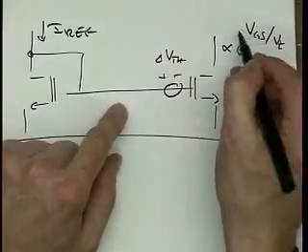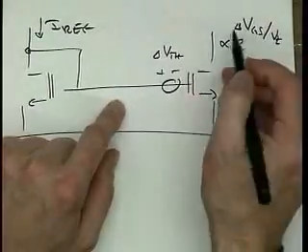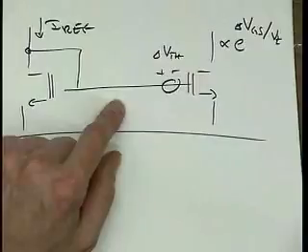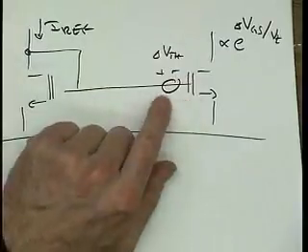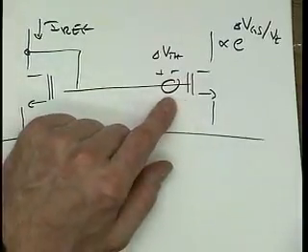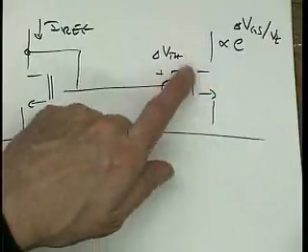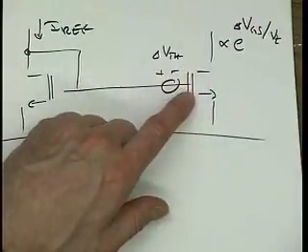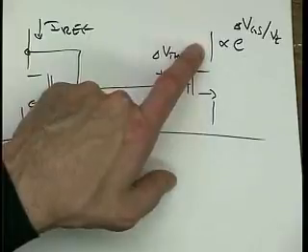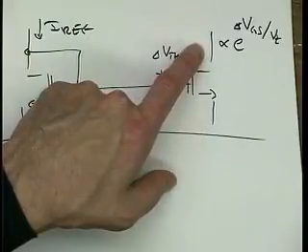Well, if in an exponential we have a little bit of a delta VGS, even if it's small, we get a huge error. In fact, delta VGS of 60 millivolts is a little bit on the steep side, but in a bipolar transistor, it takes just 60 millivolts to change the collector current by a factor of 10.